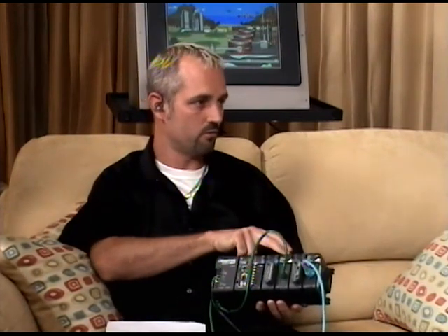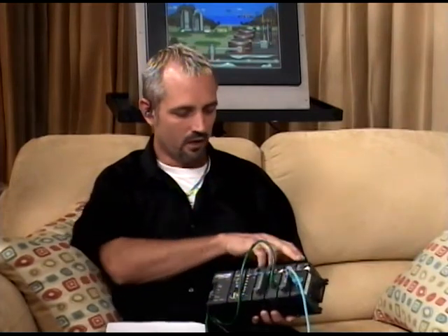We're probably going to hit some of these same topics again and again. But I keep referring to this 205. Here I've actually got 2 Ethernet devices in it. I've got the CPU, which is all serial, but then I've got an ERM, which is the Ethernet Remote Master. It's an H2-ERM. The H means Host Engineering developed it, one of our partners. The 2 means it's for a 205 rack, and then the ERM. And also I have an H2-ECOM 100 down here. Now this 100 is actually going to a hub and all kinds of other stuff.